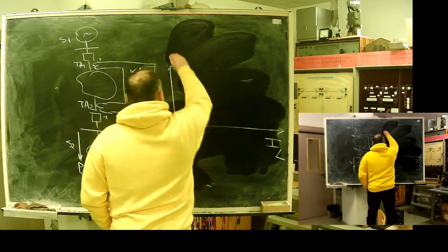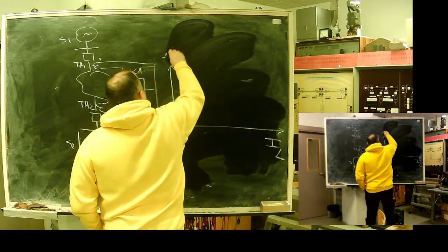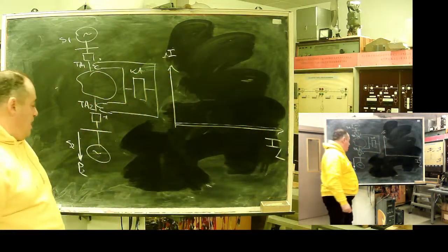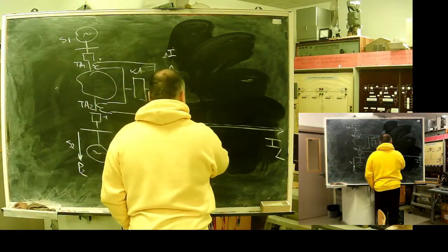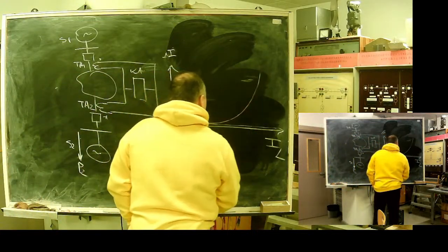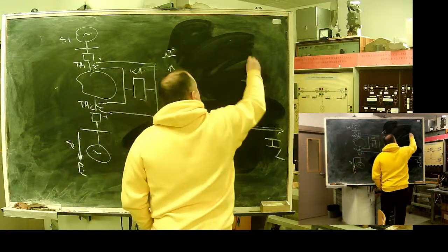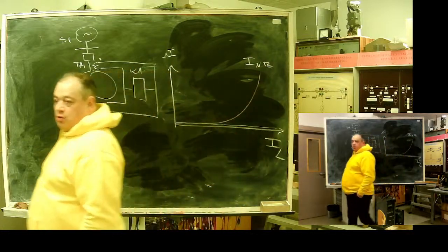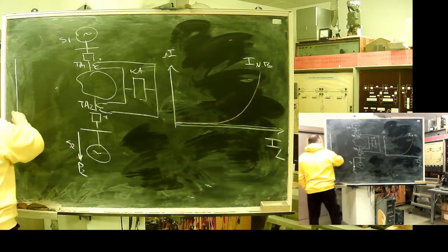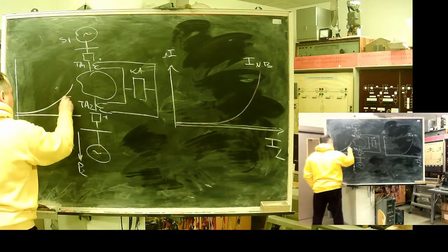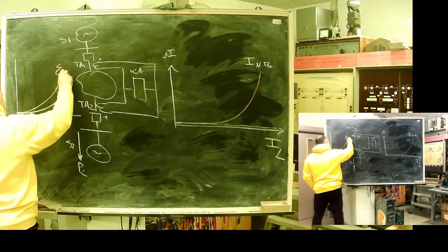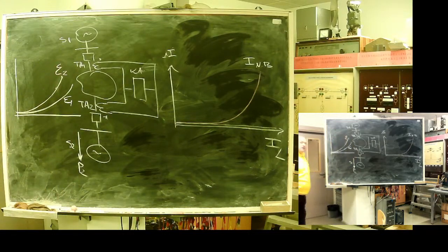In the ideal case, it should be 0. In reality, it's a so-called non-balanced current. It's a current caused by error, a characteristic of a real current transformer, any current sensor.